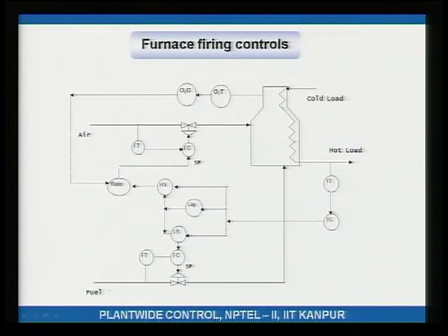Now, let us see, let us say the temperature of this stream is decreasing, it is going below the set point. Since the process stream is becoming colder, that means you need to put in more fuel and more air, so that the temperature of the process stream that is decreasing will come back up, right.